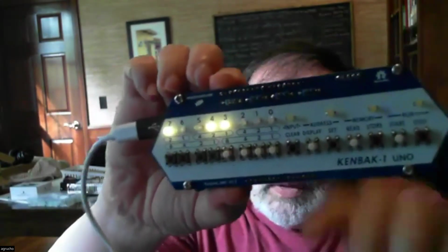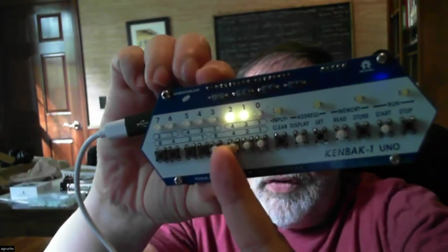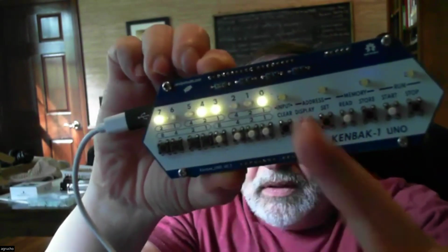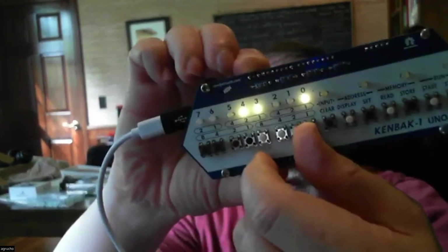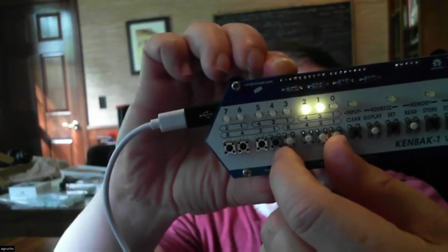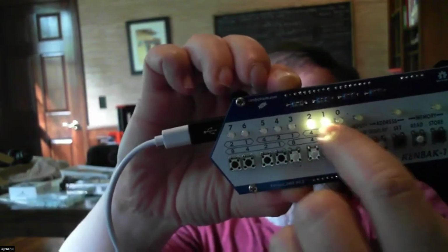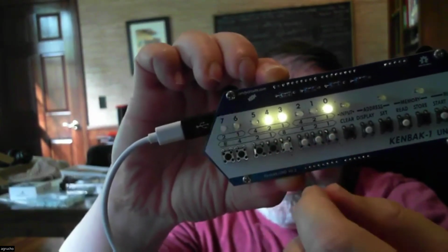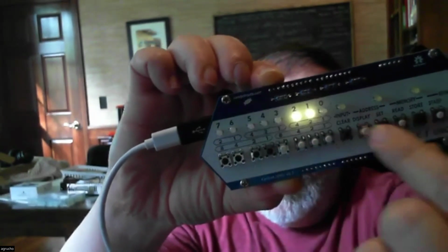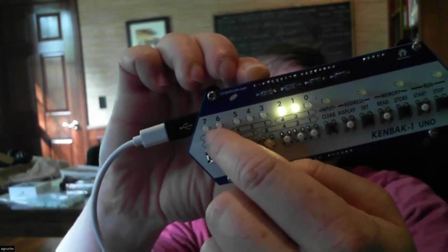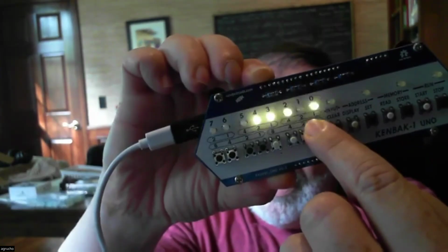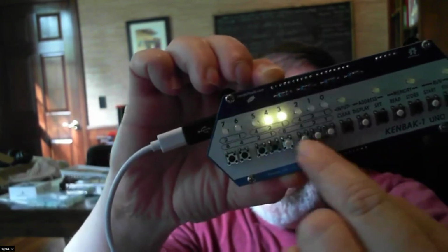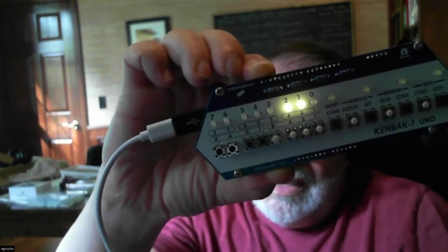You can read in BCD, four bits for each digit. You see six in binary in the lower nibble, and when this one is blinking, you see the minutes. 6 minutes here, 1 and 9. 1 and 9 is 19.